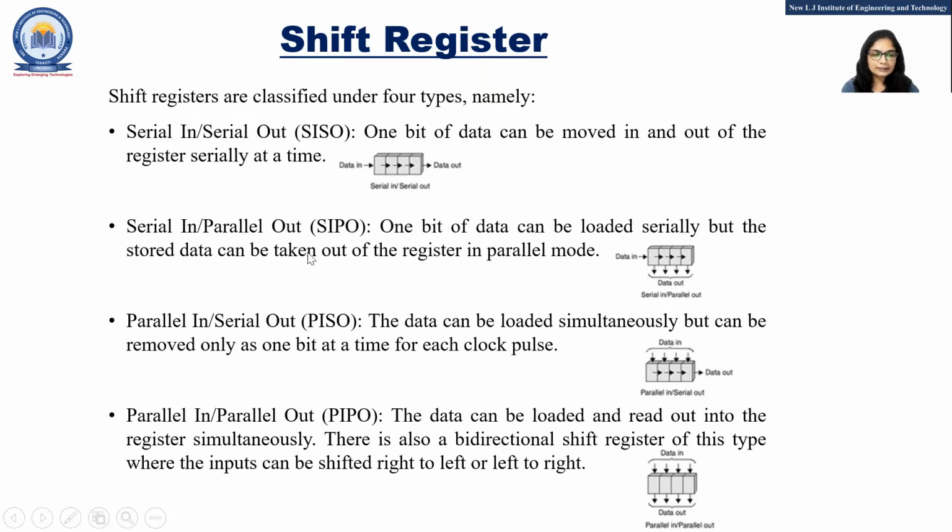Now next, serial in, parallel out. In this register, data can be loaded serially, but we take data at the output terminal in parallel. Means simultaneously, at the same time, we can take data at the output terminal. So this is quite fast compared to SISO.